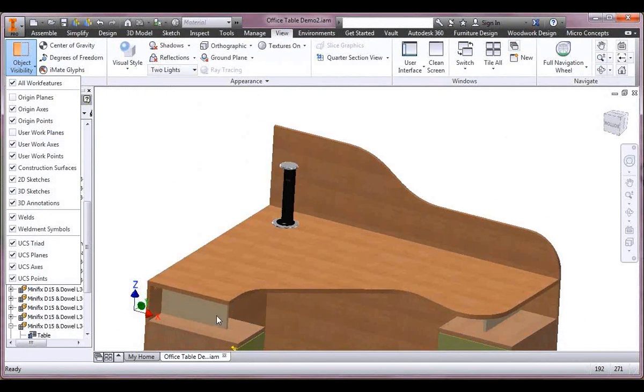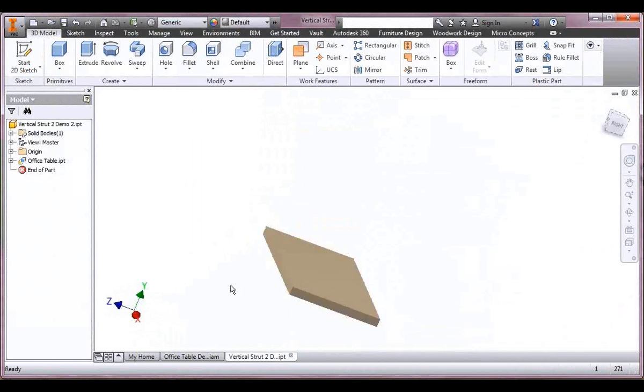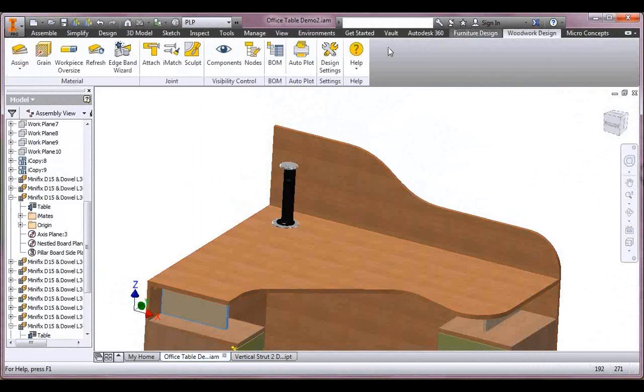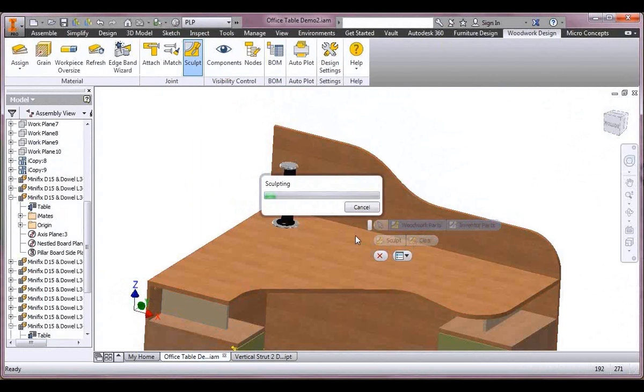So I don't put the hole in the panel, I let that unit put the hole in. And you can see that's the basic interconnection there with no holes in. If we use the sculpt tool, it drills straight through the whole assembly, even those drawers with all their sub-assemblies, and drills every occurrence. Every time it sees one of our negative surfaces within the actual model, it will remove that material. If it sees a positive joint, it will add that material at this point as well.